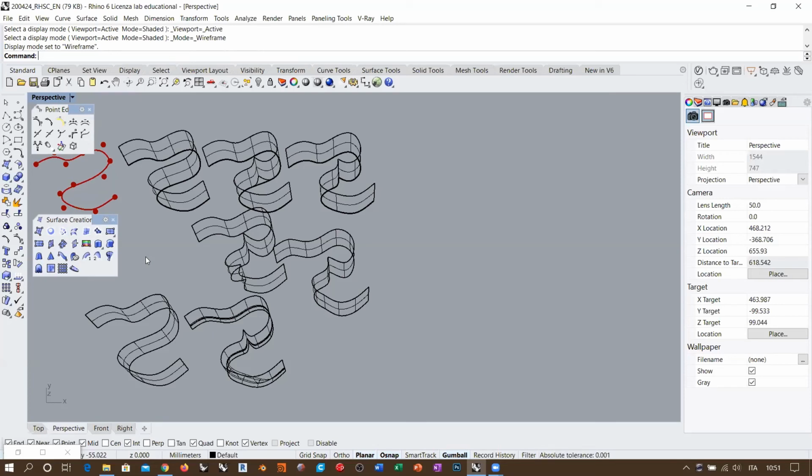And the simplest between all of these surface creation methods is using the loft. The loft is an extremely powerful tool. So I do recommend that when you need to create some complex geometry, some complex surface, first check if you can do it using a loft, because the loft gives you the perfect balance between complexity control and geometrical control. So you normally should get the simplest possible result, also with very complex geometries.